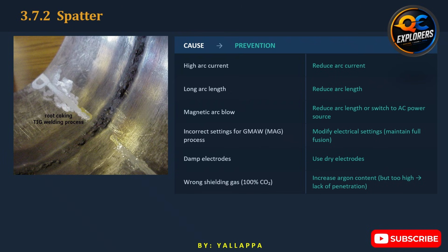In pressure vessel and pipeline work, adhering spatter may need to be removed before final inspection because it can trap moisture, interfere with surface examination or violate project requirements. Therefore, the inspector should not simply say, "Remove spatter." Where excessive spatter is observed, investigate the welding conditions that produced it.